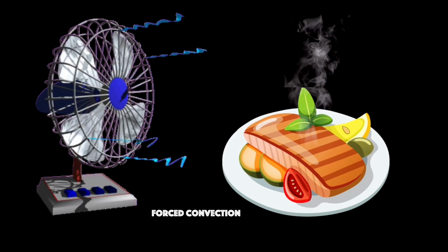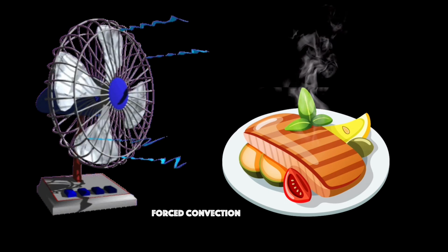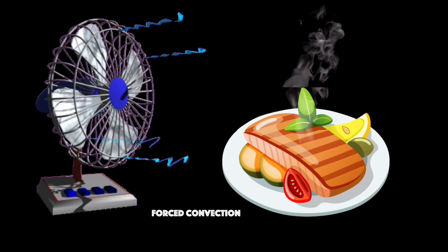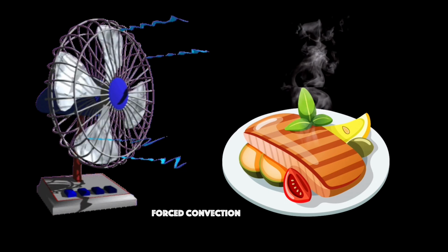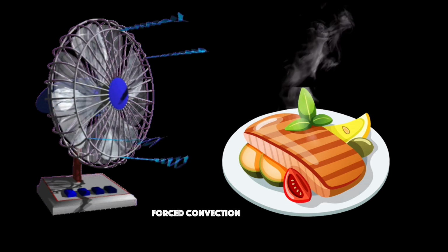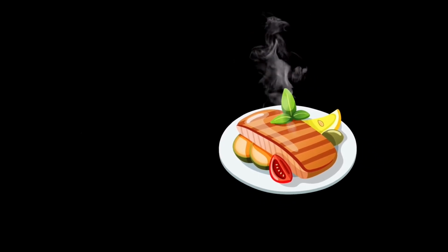Forced convection is categorized when the fluid is forced to flow over the surface by external means like a fan, pump, or wind. While natural convection is when the fluid motion is caused by buoyancy forces induced by density differences due to the variation of temperature in the fluid.